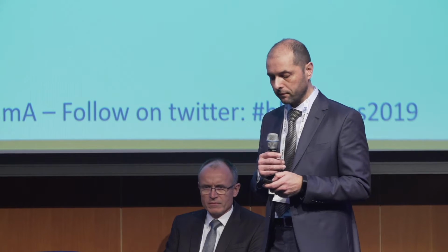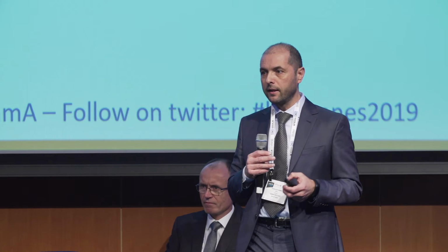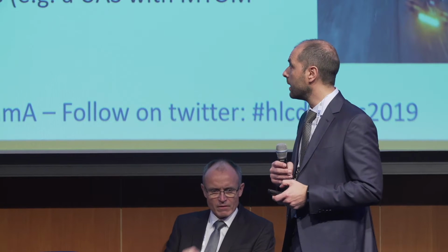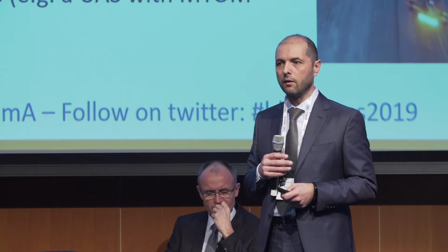The operator needs to register in the open category every time they use a drone with a maximum takeoff mass of more than 250 grams, or when the drone is lighter than 250 grams but is equipped with a sensor able to capture data that are sensitive for privacy, so we're talking about a camera or microphone, or when there is a high-speed drone, meaning a drone that in case of impact with a person can transfer an energy of more than 80 joules, so it can be dangerous to people.